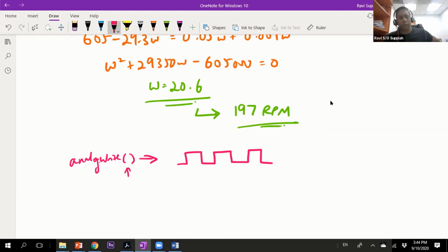The good part of Arduino is there's always a lot of online help and resources with sample code. Anytime you don't know anything, you just Google for it, look at some sample code, and from there you'll figure out what to try, and see what happens. The only thing about the analogWrite function is it only works on pins which have PWM capability.